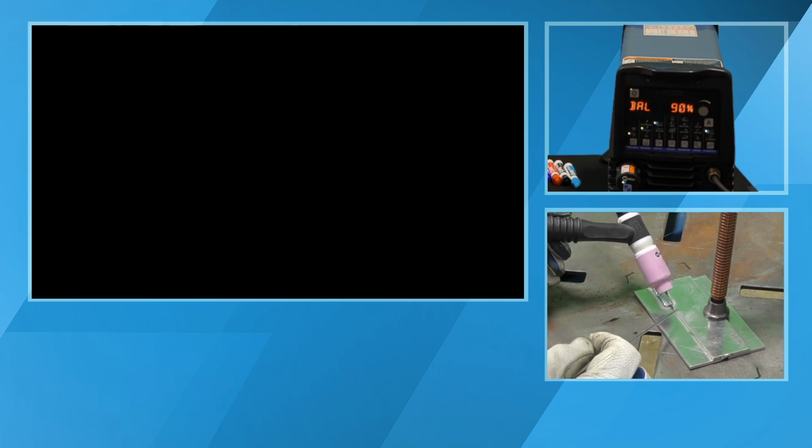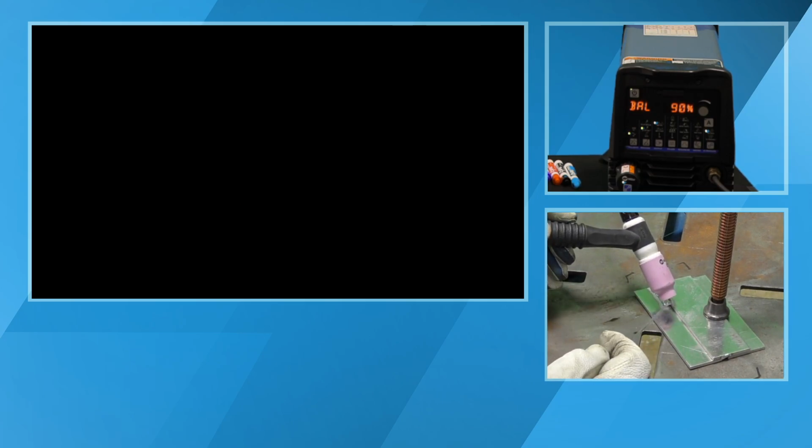Now I'm going to go over here and I'm going to turn my balance setting up, and we're going to go up to about, let's start at 90% electrode negative and see what happens here. Now, when I'm welding on this, it's going to probably completely eliminate this white etching zone next to the weld. It's also going to end up giving me some oxides in the surface of the material that looks like someone took a pepper shaker on top of my nice shiny weld puddle, and that's going to be those oxides floating on the surface that we talked about. So I'm going to put my helmet down, and we can go ahead and get started.